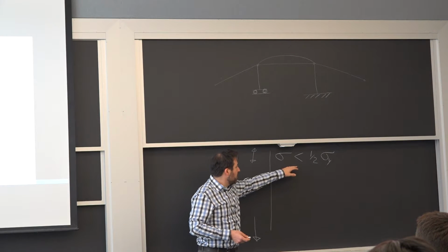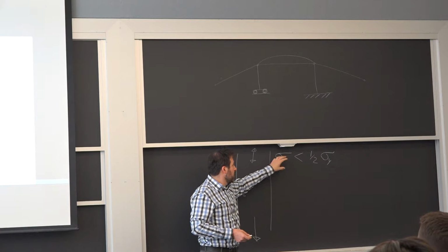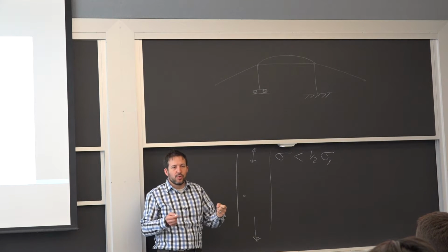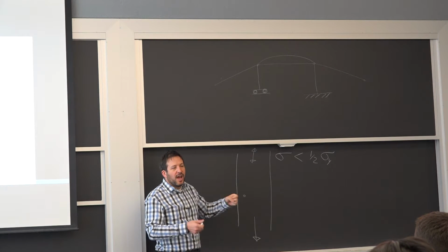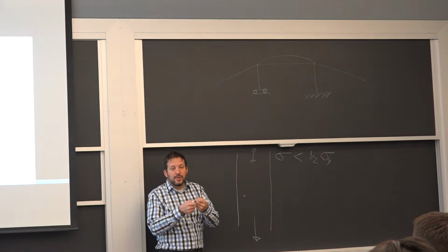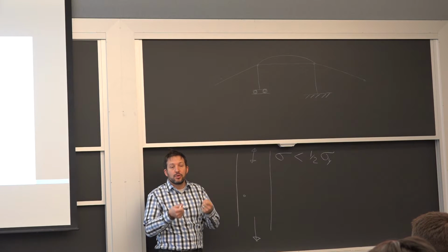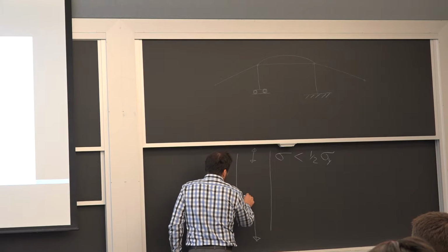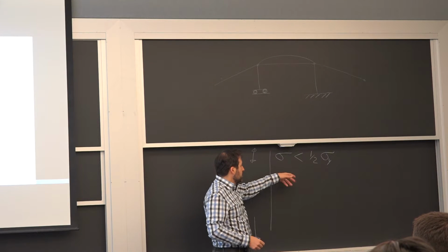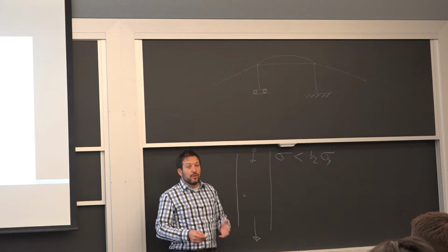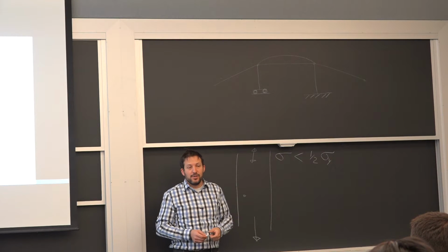So if you're above a certain threshold, even though the entire member is elastic, just like a spring, locally you start having this real plasticity, like a permanent local deformation, and that will create the initiation of the crack. So on a metal, you can set a criteria, especially steel. There will be a certain value below which you're okay. You will not initiate a crack.